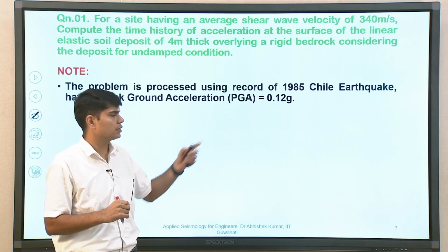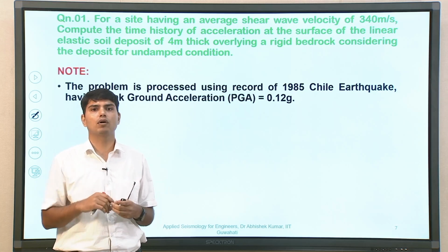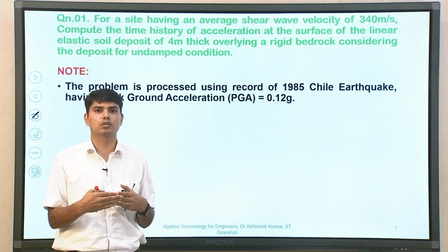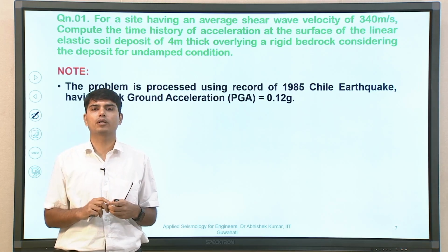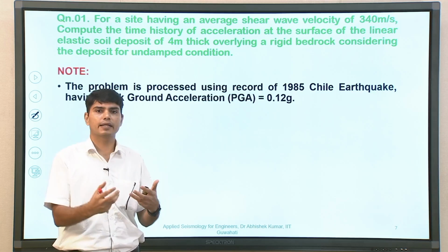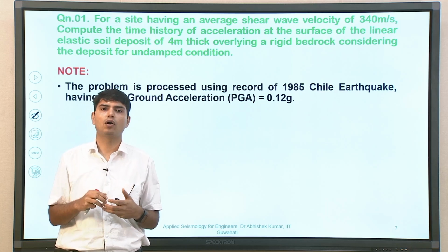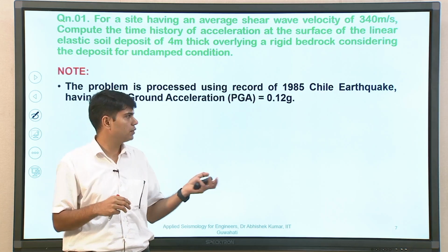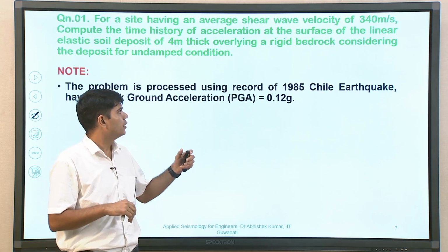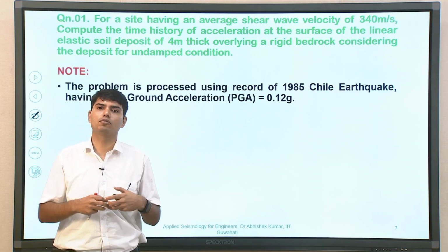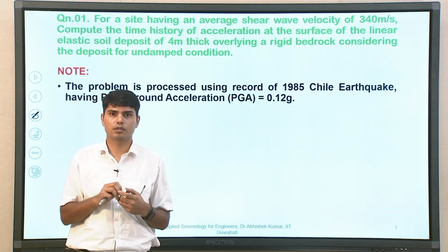As far as motion selection is concerned, you can go with seismic hazard analysis, find out the expected level of bedrock motion or site class A motion expected at your site of interest, corresponding to that value of peak ground acceleration or PGA, and select a motion from a region having comparable seismic activity, or generate synthetic ground motion, or use a regional ground motion record if available. If none of these are there, and you are doing ground response analysis, then you have to be very precise that you have done the analysis considering this particular motion.